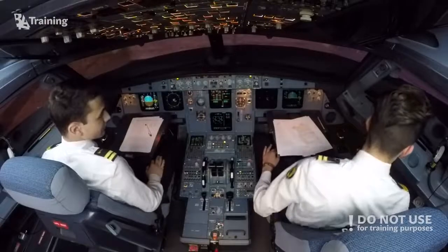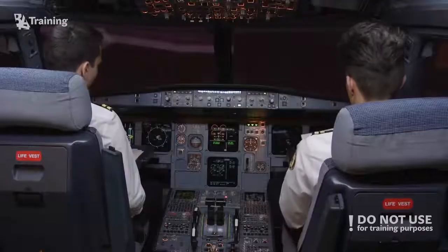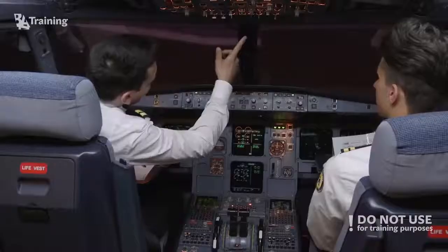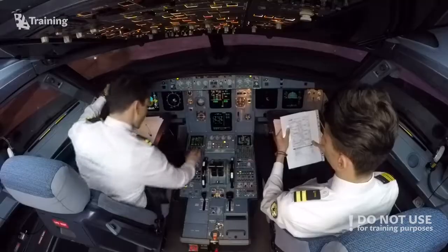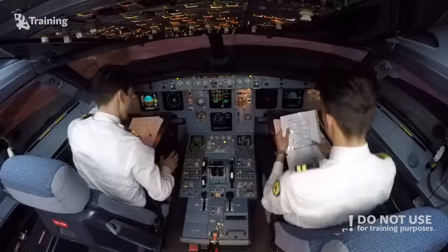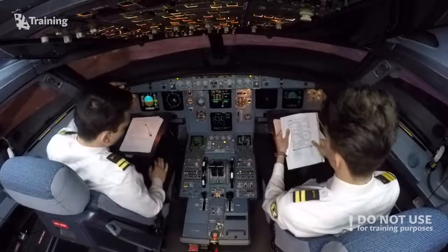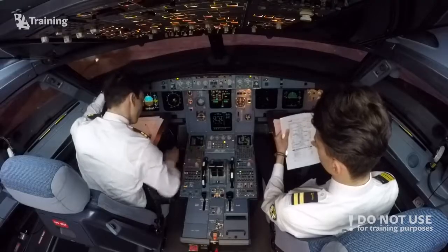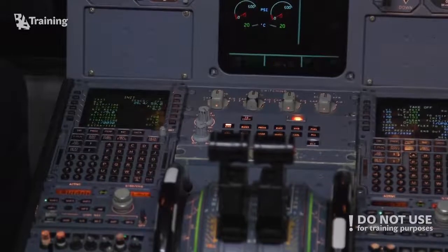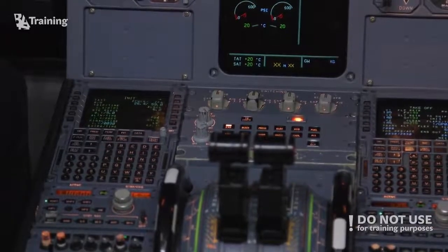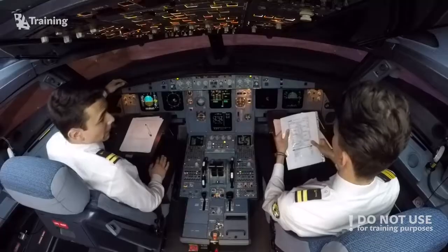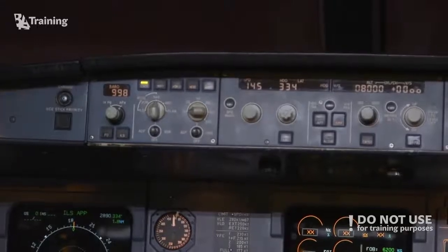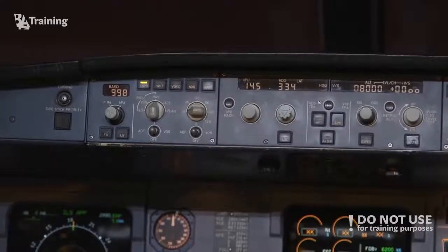Okay, before start checklist. Before start checklist, cockpit preparation? Completed. Gear pins and covers? Removed. Signs? On, auto. ADIRS? Nav. Fuel quantity? Fuel quantity 6,200 kilograms. Takeoff data? Takeoff data: zero fuel weight CG 26.4, zero fuel weight 59 tons, block fuel 6.2 tons. Set. Baro reference? Baro reference QNH 908, 1,400 feet. Set. Down to the line.